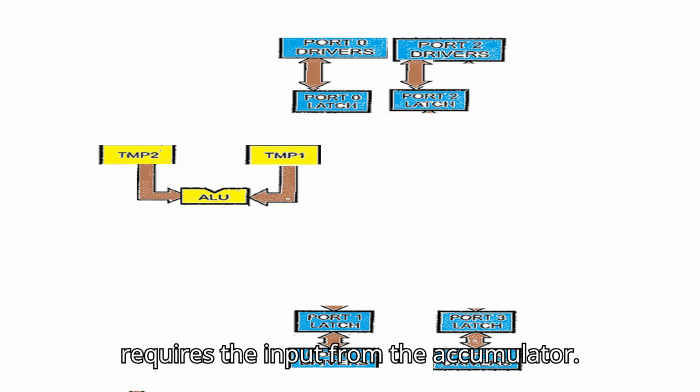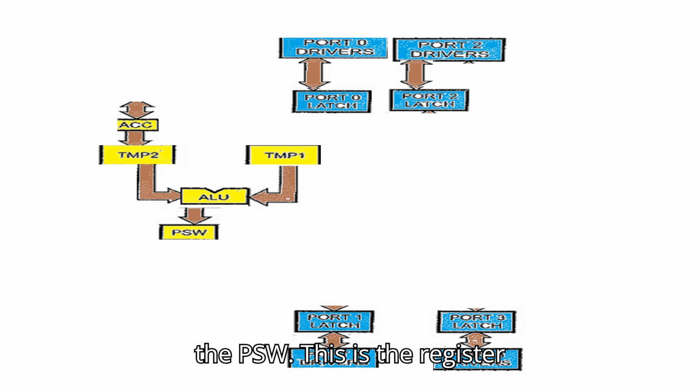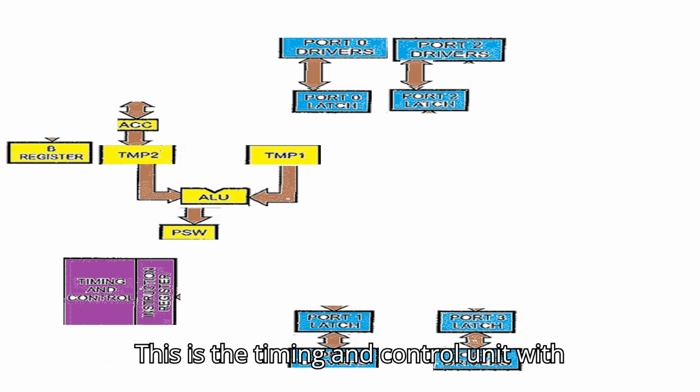The center part of the microcontroller is the CPU, which consists of the ALU. It is used to perform arithmetic and logical operations. For performing any operation, the ALU requires 2 inputs, temp1 and temp2. For performing an arithmetic operation, the ALU requires the input from the accumulator, and the status of the result is shown in the PSW. This is the register B. This is the timing and control unit with instruction registers, which has the pin connections PSEN bar, ALE, EA, reset.